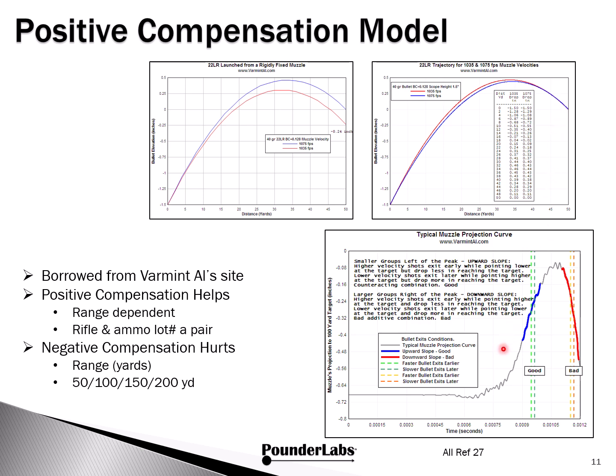Let's zoom in on this particular rising, falling part of the barrel vibration. Here in the blue area, if we're catching it on the upswing and the faster bullet exits earlier than the slower bullet, we get this kind of behavior, which is good. But notice the other side: if we catch it on the downswing, it actually makes it much worse, because the faster bullet exits earlier and gets there quicker than the lower speed bullet.